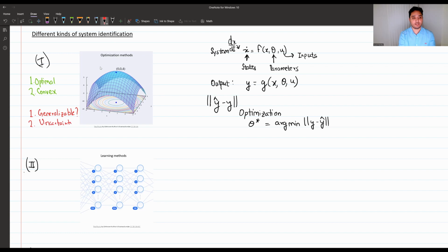Uncertainty in the data is quite common. Any system working in real environments will exhibit noise and uncertainty. But those are not undesired behaviors, because those will always be the same whenever system response is measured. So our parameters should reflect that ideally, and not just be one value, because that one value is representative of that particular experiment. So we want to find out how uncertain the parameter values are, and that's not straightforward with this method.